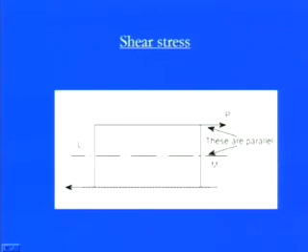That is why we can say that the stresses induced by these forces are shear stresses, and they are well established within this region. So we must know at which region within this object the shear stresses are maximum, so that we can easily design those components by taking different values of the factor of safety.